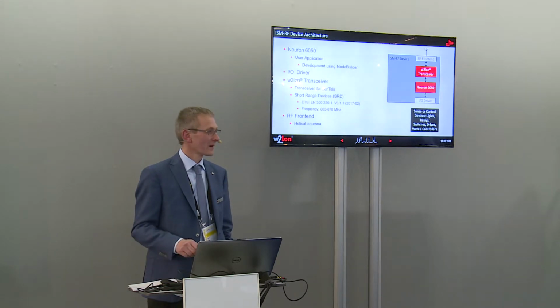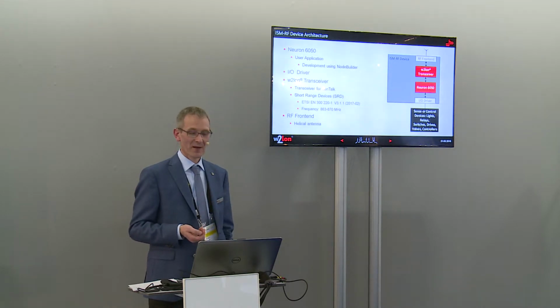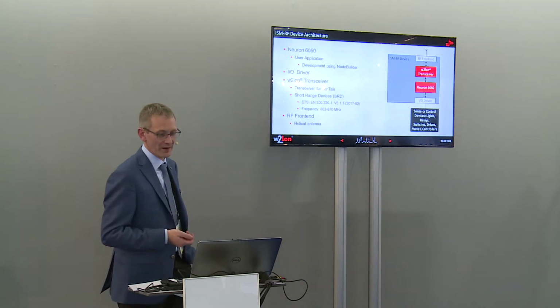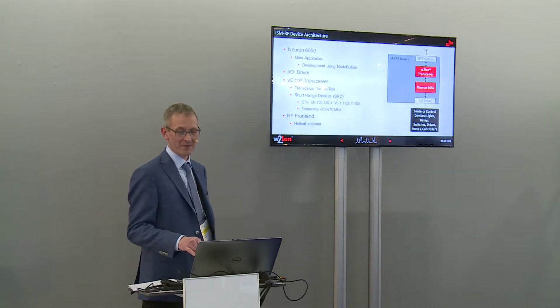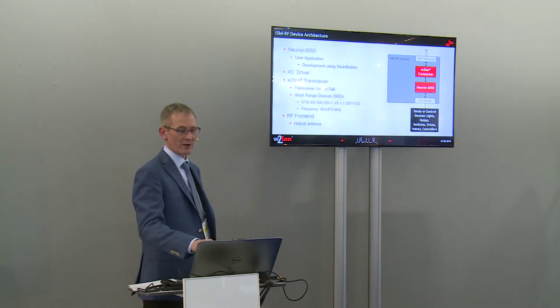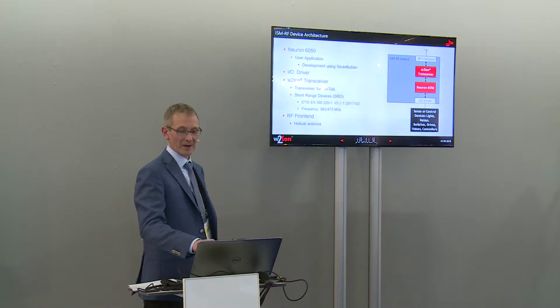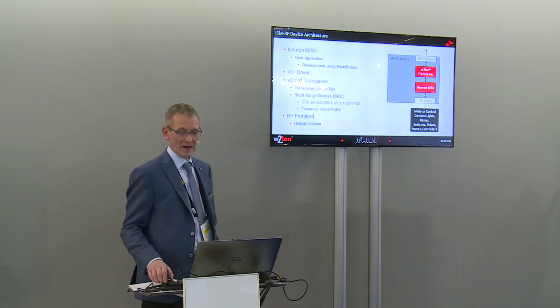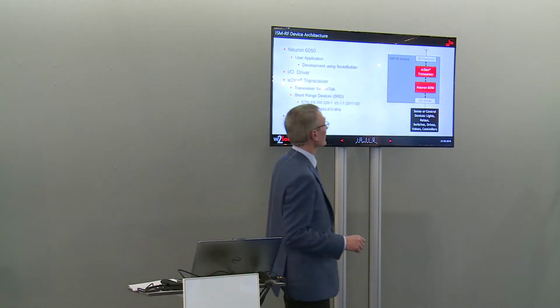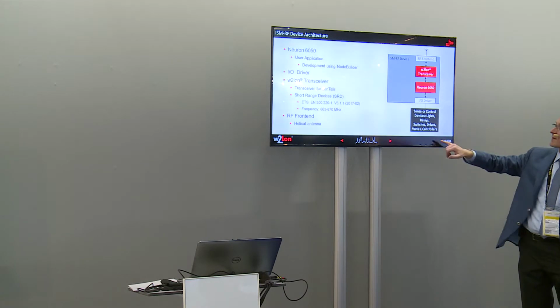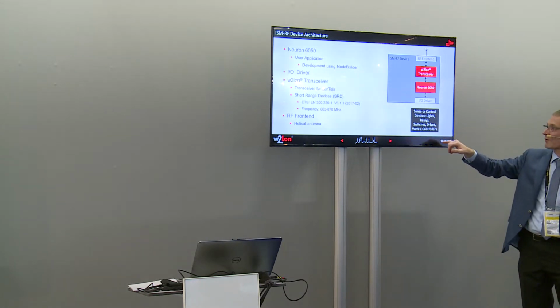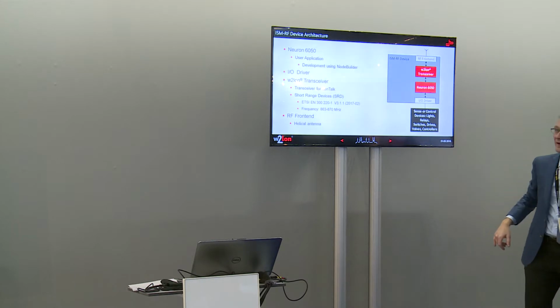Okay, this would be the architecture of an ISM RF device. Based upon the WT-LON transceiver, an ISM RF transceiver. We would use the Neuron 6050. We connect via the communications port, and we do have an RF front end to connect to our radio system, and of course we can connect different sensors and control devices via the I/O driver.